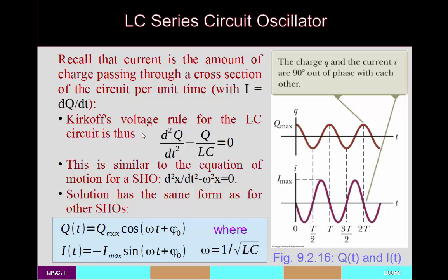And so you end up with some rather interesting solutions for that. Basically, you end up getting damping, and moreover, that damping basically depends upon stuff like what frequency you are trying to damp at. There's basically what's called a critical frequency, above which you are going to have difficulty getting oscillations.